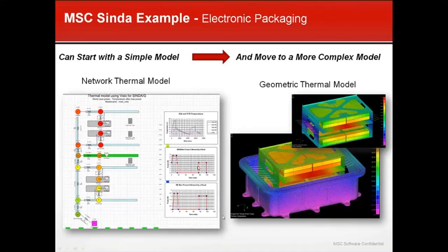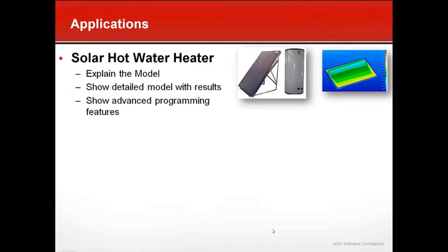ran transient powers and recovery times and things to see what the duty cycle could be on this box for storing data and dumping data, and came up with a design and then went to a detailed finite element model to get the gradients. So it's not uncommon to start with a simple model, which may give you all the information you need, but then you can take it to a more detailed model.